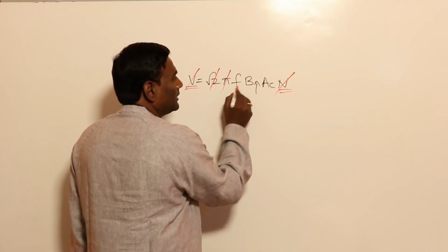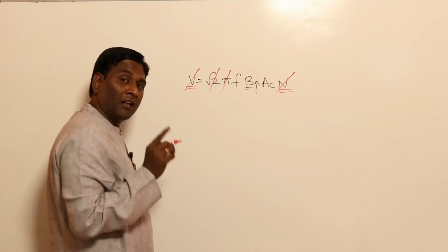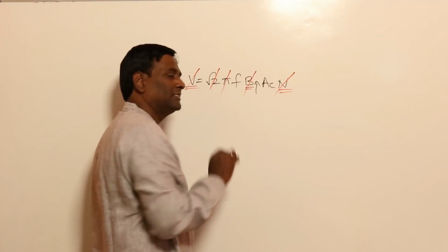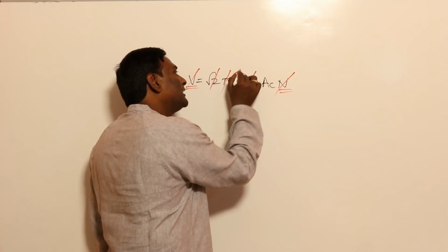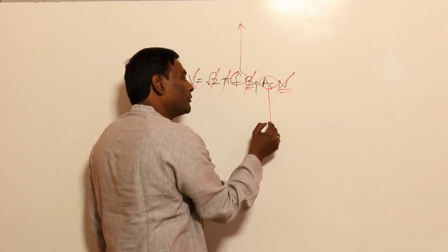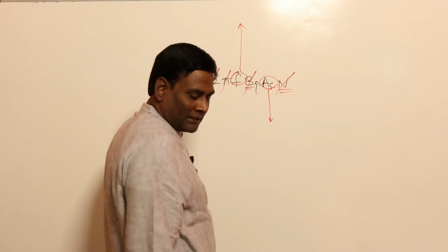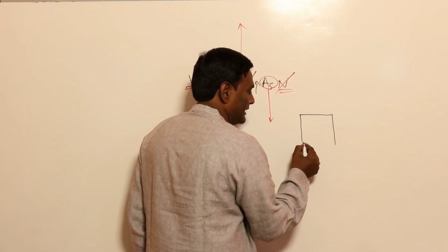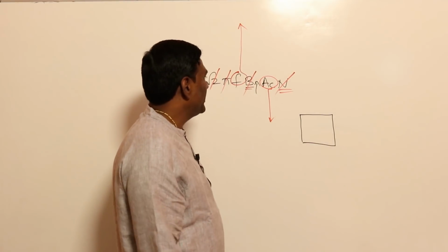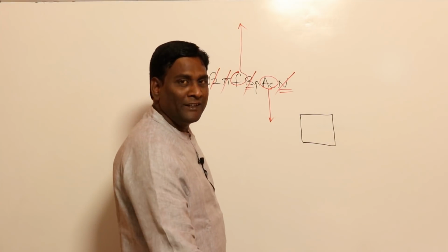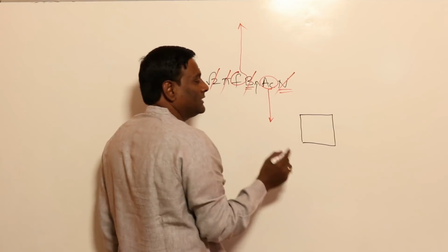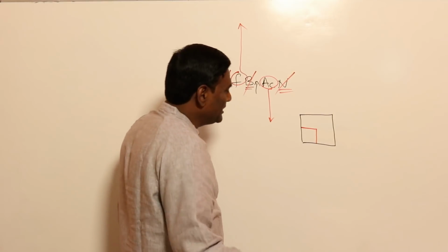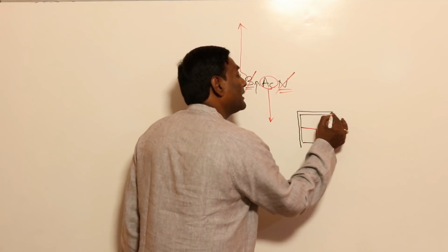Under that condition, for given flux density, because we already know that flux density is not a term to play with, if I increase frequency, the area of cross section of the core will be reduced. Means that, for example, this is the area of cross section of the core in the first case, the black case. If I increase frequency, what about the area of cross section of the core? It will be reduced.